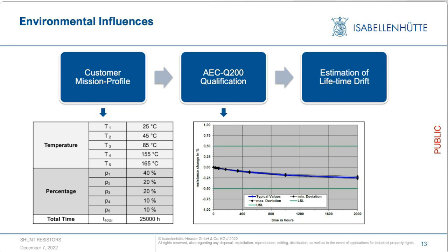So far we have built a huge database of different shunt designs, simulations, test results, and the final estimation of the lifetime drift, so that we now have really good statistical evidence to estimate the lifetime drift even during the development phase of a shunt.